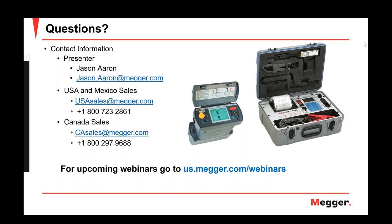Now, the setup to use it with PowerDB is similar. You're going to find the export menu on the receiver and select that. Once you select that, it's going to give you an option to either export that data to the printer or export the data to your computer. To connect the receiver to your computer, there's a cable that's provided, and on one end is going to be the connection for the receiver, and the other end is going to be an RS-232 connector that you can connect to the COM port on your computer.